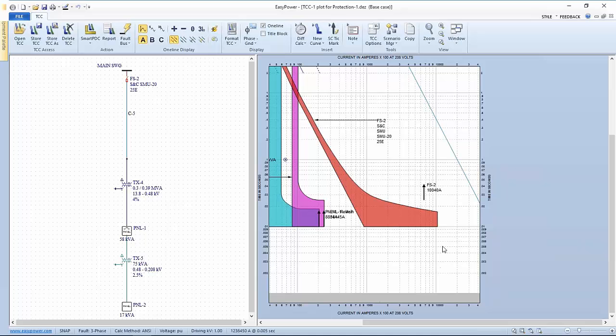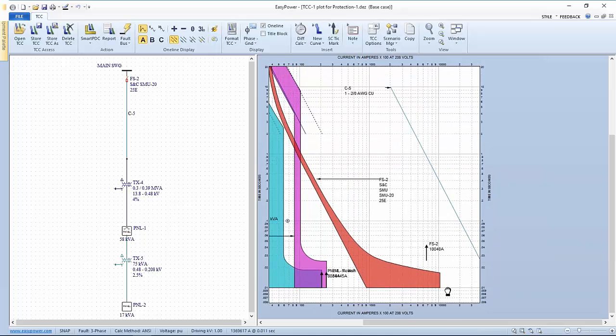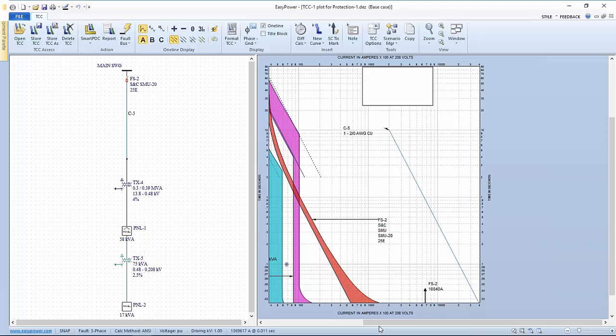If we look down here on the scale that we're actually indicating, that tick mark is actually, because we're multiplying by 100, here's 100,000, so 160,000, so this 10,000 amp fuse won't trip until we get 600,000 amps, which causes problems.